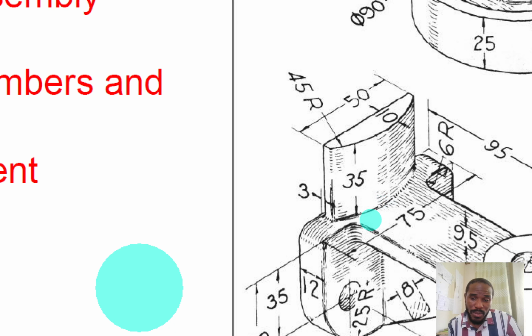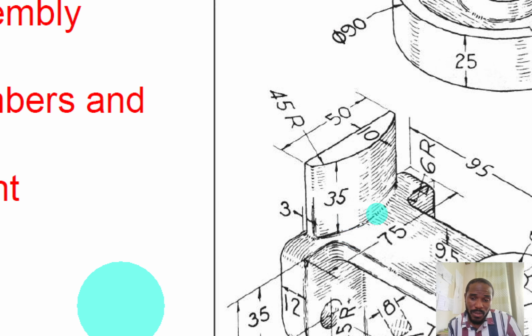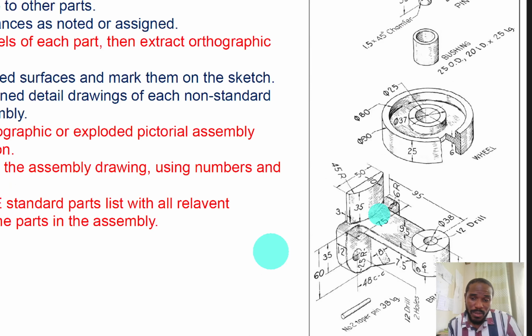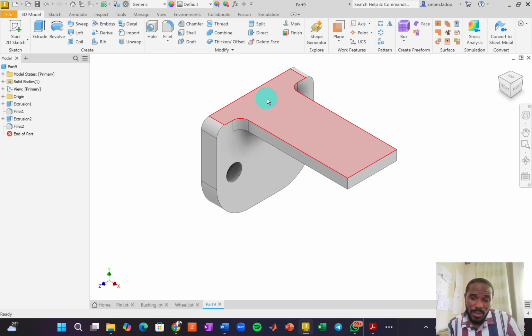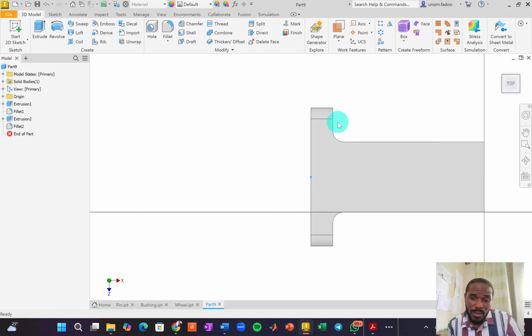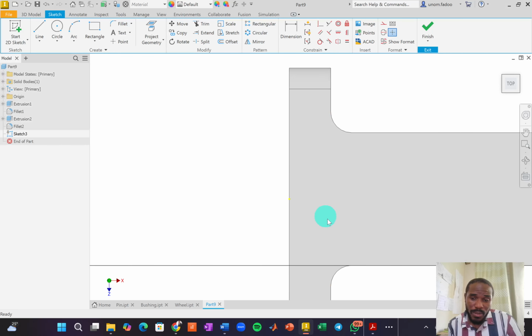Then when we come to extrude, we extrude by 35, okay? So let's get, now I'm drawing on this face, so I'm going to hover over that face until it's highlighted. I'm going to left click and then click on the create sketch icon. Okay, now I'm going to zoom in a little bit. I'm going to pick my 2-point rectangle tool somewhere there. I'm going to draw that. The thickness again was 10, right? Tab. The length was 50.